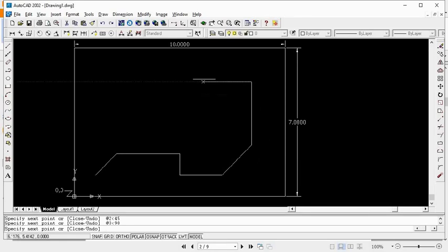And like that, again, something to note also is that you can show the direction. The dotted line tells you that the line is moving perpendicular. So at 180, I can just put 1 and enter. Then show direction again, the dotted line, 1, enter.